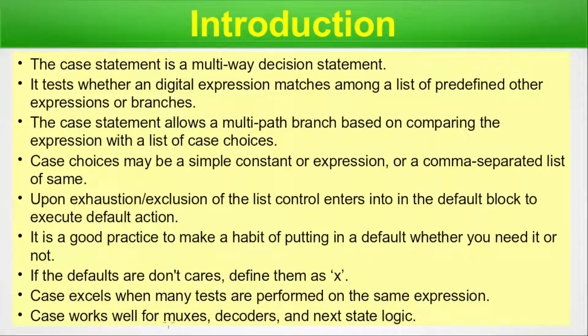Case works well with which digital circuit? Muxes, decoders and next state logic. And the next state logic is also termed as the FSM in digital design. In some later episode we'll cover muxes and decoders, you already know. So those things go well with the case statement. So we're done with the introduction part here and with this slide. So let's move on to the next slide.